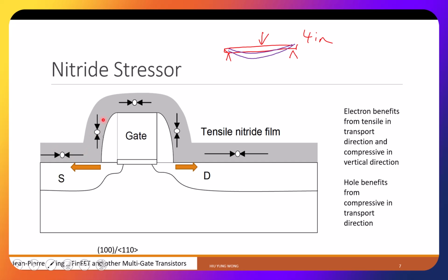Because nitride and the substrate have different thermal expansion coefficients, what it means is that when you change the temperature, your material is going to expand or contract, right? Some material expand and contract faster than the other. So you start at very high temperature. You deposit the nitride, okay, there's no stress because you deposit means you just grow chemically, right?